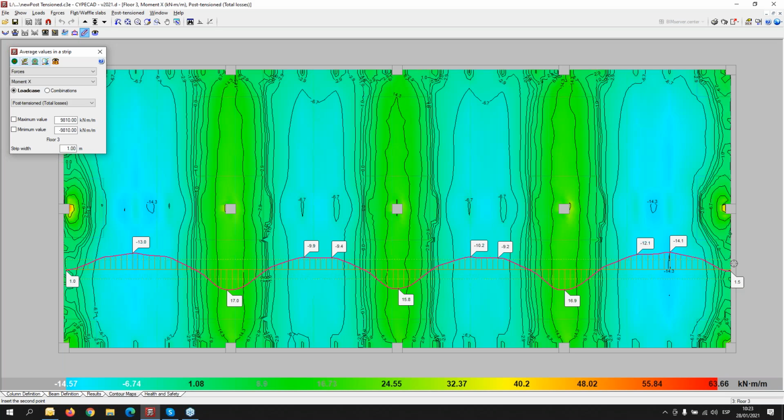It may be interesting in this case to compare the stress and the forces applied by the self weight and the stress, in order to apply a criterion to have an order of how much of the self weight of the slab may be equilibrated by the forces applied by the post-tensioned elements.